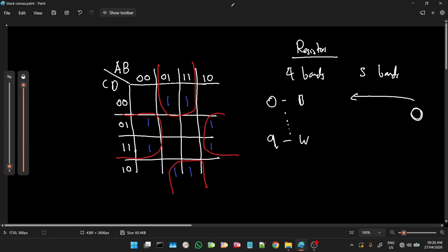The last band will always be the tolerance band. The tolerance band goes from plus or minus 1%, plus or minus 2%, to 3, 4, 5, and then anything else that doesn't have a color is, I think, 20%.